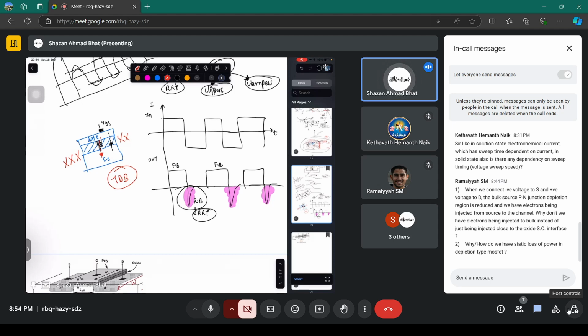Why detrimental? Because it will cause the capacitive action to be lost. If charges start to flow through the oxide, the charge will reduce, and the capacitance will reduce. The capacitance is the major factor in controlling the channel. If there is no charge at the metallic plate that stays there, it cannot induce the opposite charge in the channel. That is a very degrading factor, and you cannot even control the channel. That's not going to happen. So that is the overall scenario.